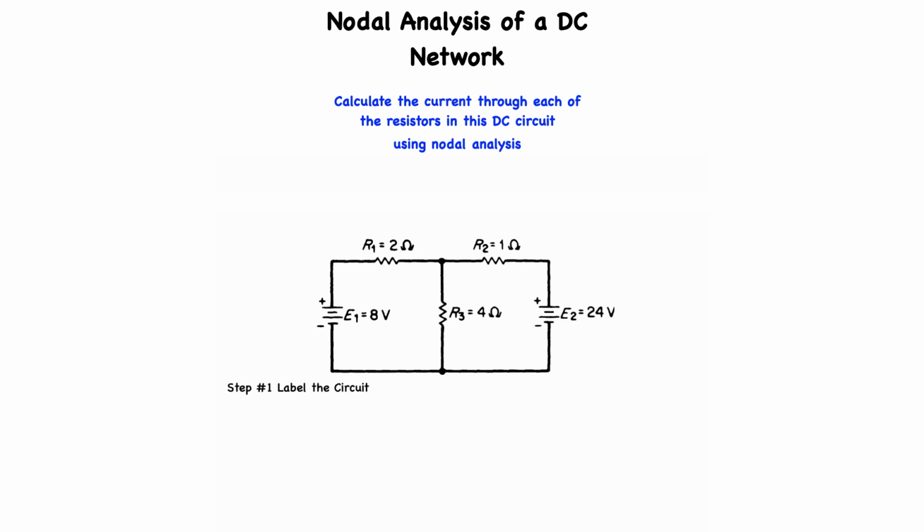Step 1. Label the circuit elements, all nodes. One of the nodes, node A, is chosen as the reference node. It can be thought of as circuit ground, which is at 0 voltage or ground potential. Node B and node D are already known to be at the potential of the source voltage. The voltage at node C, the voltage we call VC, is unknown.